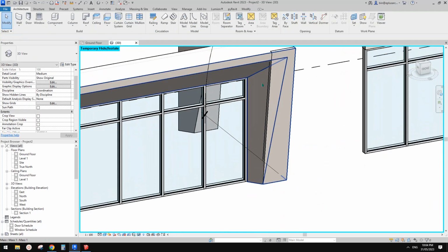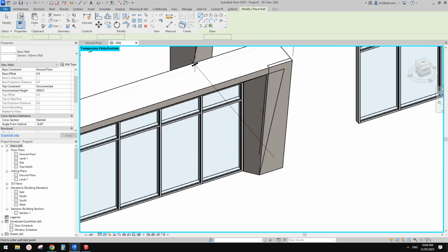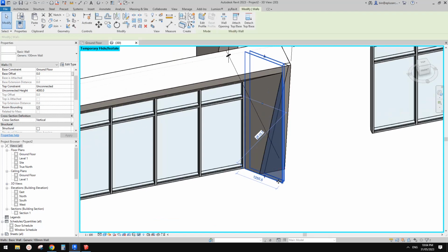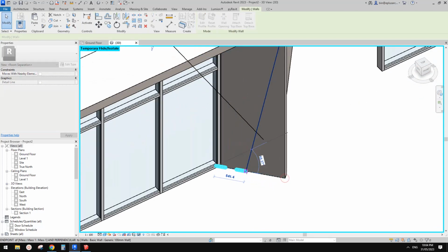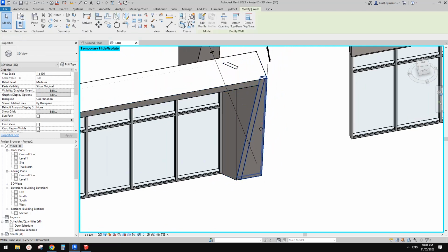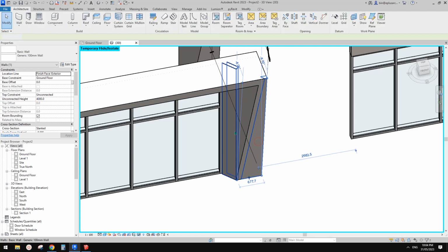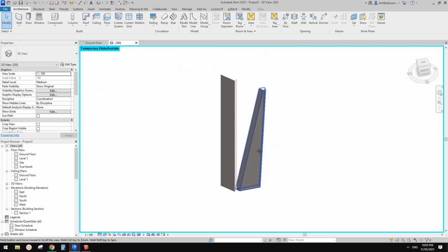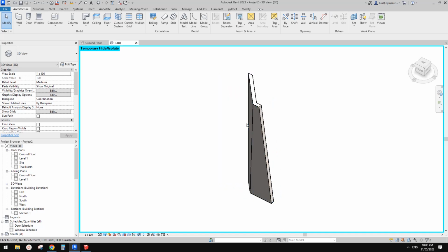So, and then how about this part? So that's fine. So CS, create another one, pick line, finish face exterior. Good. Probably not 8 degree because this surface, I think it's vertical, so 0 degree. And pick this edge. Okay, so I don't need to go back to here. Now you can see we have these two walls. So I'm going to select these two walls and type HI, so isolate. So only have these two walls. I try to trim it. So now you can see it will automatically create this, which is quite nice actually.